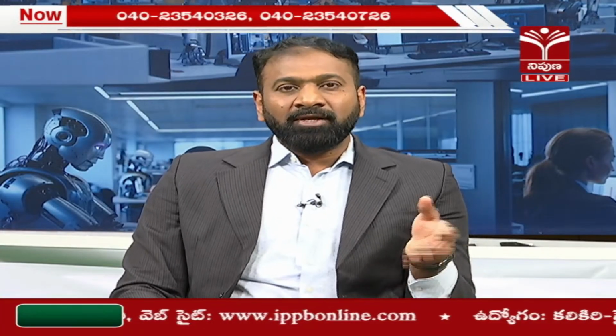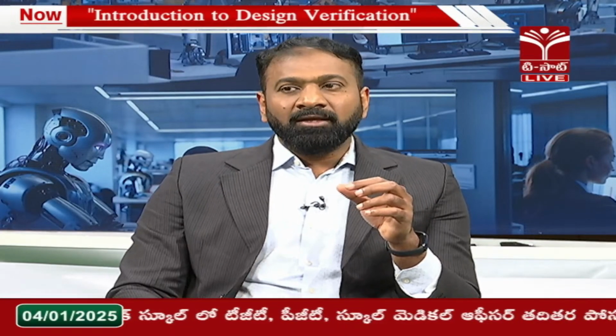Now, just to quickly introduce SystemVerilog, why a SystemVerilog environment? One thing we understood is this is like the difference between C and C++. For people coming from a software background, it helps you with higher level objectives and a higher level encapsulation of your design. So, the key building blocks of SystemVerilog are two blocks which are available here, the program block and the interface.